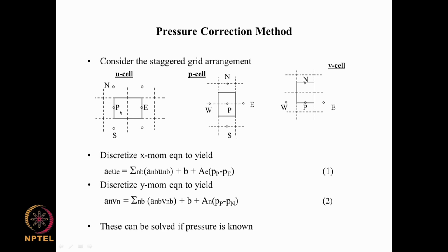These are where pressure is evaluated. If you take this particular cell here for the pressure, pressure is evaluated at capital P, the immediate point at which pressure is evaluated on the east side is denoted as capital E, the immediate location where the same quantity P is evaluated is capital N, capital W and capital S. And if we put a control volume lying halfway between the 2 points on the east side, west side, north side like this, then we can associate with the faces of this control volume the midpoints.